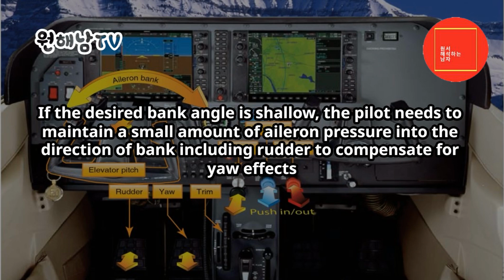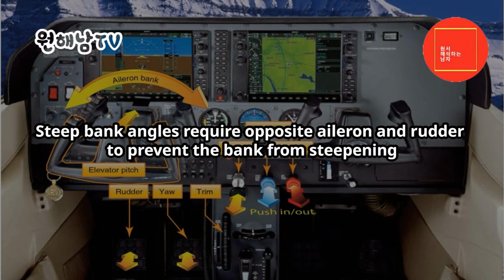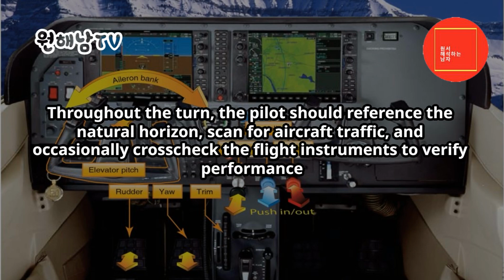If the desired bank angle is shallow, the pilot needs to maintain a small amount of aileron pressure into the direction of bank including rudder to compensate for yaw effects. For medium bank angles, the ailerons and rudder should be neutralized. Steep bank angles require opposite aileron and rudder to prevent the bank from steepening. Back pressure on the elevator should not be relaxed as the vertical component of lift should be maintained, if altitude is to be maintained. Throughout the turn, the pilot should reference the natural horizon, scan for aircraft traffic, and occasionally cross-check the flight instruments to verify performance.